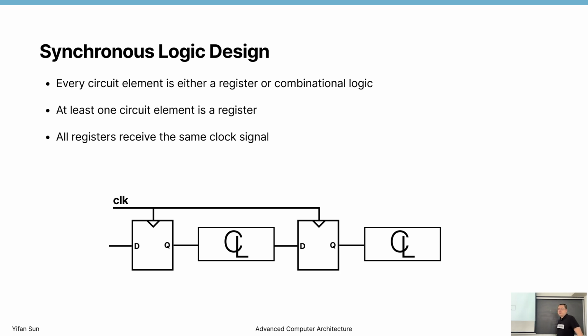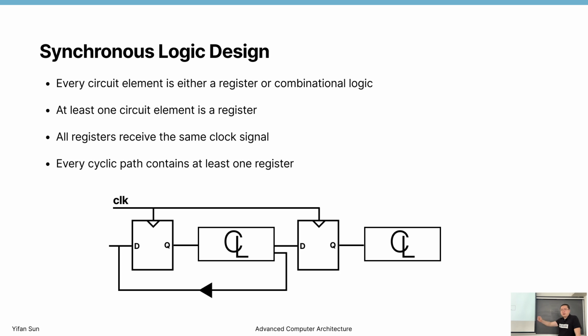So registers, you can consider in many different mental models. First of all, it's a gatekeeper. It only allows the signal to pass through at certain rising edges. The second thing, you can consider it as a 1-bit memory. We memorize data for 1 bit, 1 register, 1 bit. So the combinational logic will take that bit as an input to generate some output.